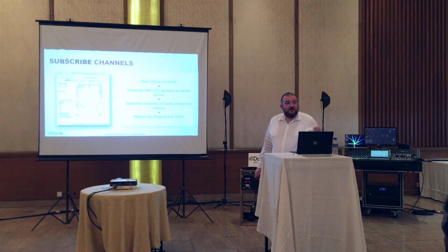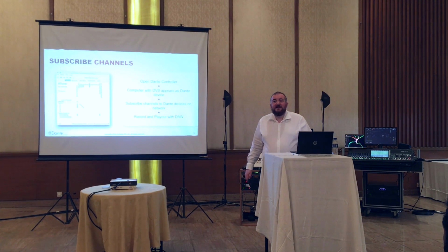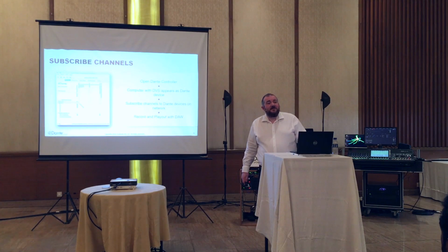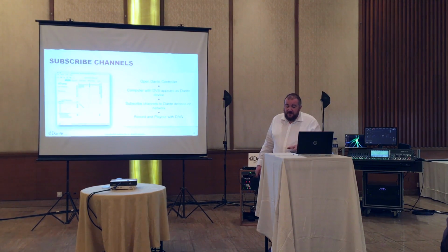So, a few things about the software sound card. Its minimum latency is 4 milliseconds. It can also do 10 milliseconds latency as well if it's a slower machine. Obviously, it's a software device, so Dante Virtual Soundcard can't be a master clock to the Dante network. You would need a piece of hardware to do that. So that's the constraints of it.